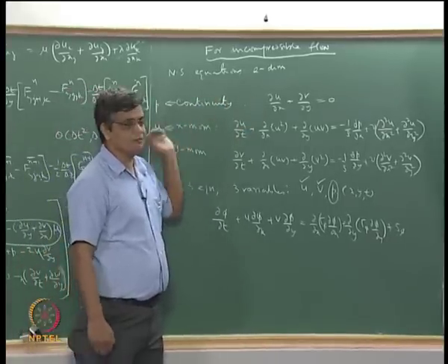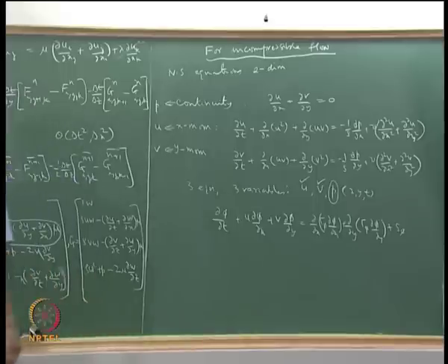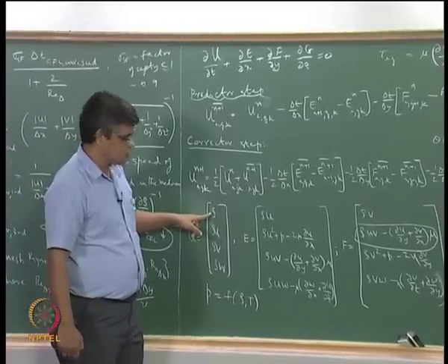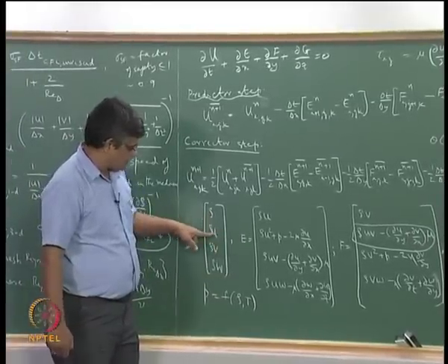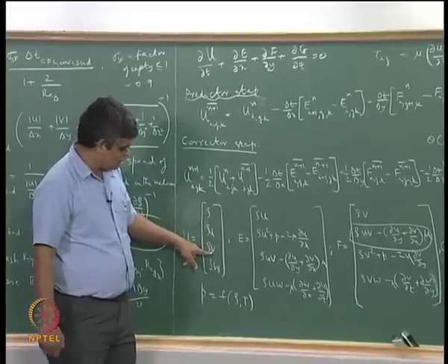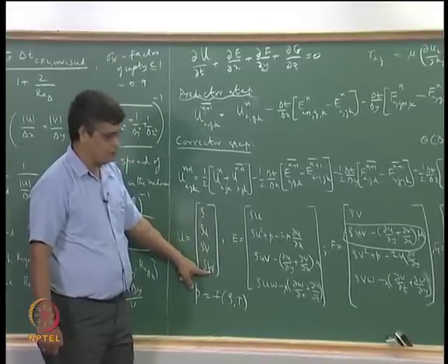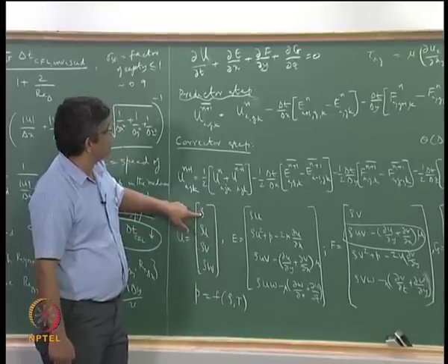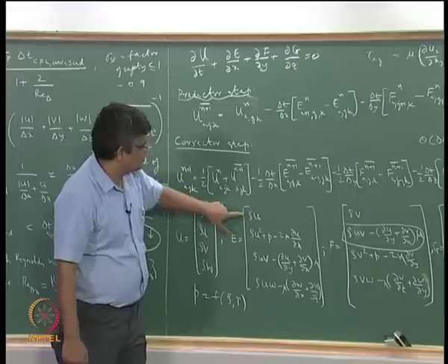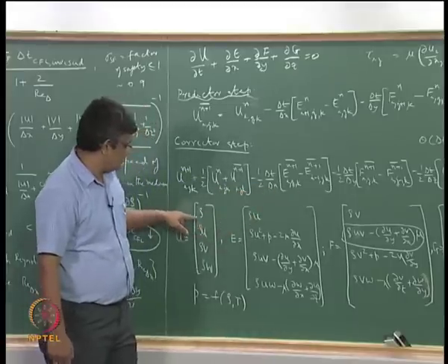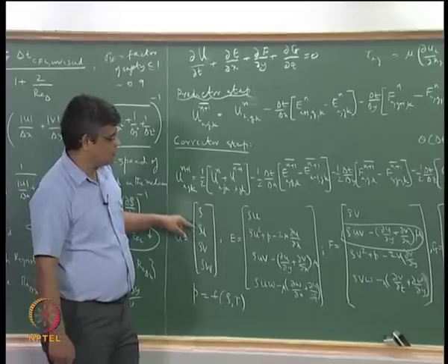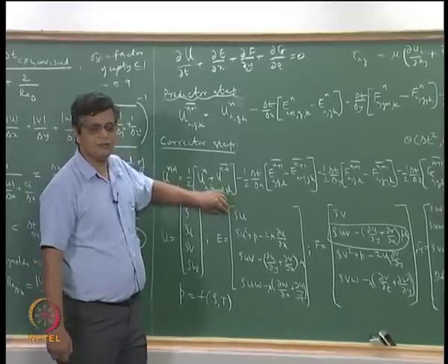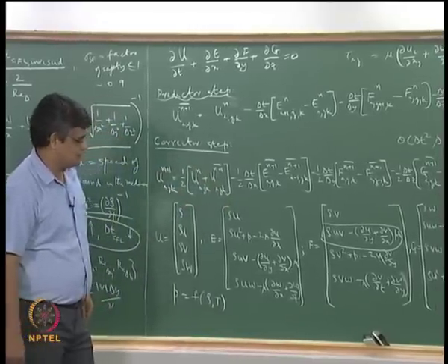We do not have the problem in compressible flow, because in compressible flow we are not solving directly for pressure. We are solving the continuity equation for rho, and the x momentum equation for u, the y momentum equation for v and the z momentum equation for w. So we are making use of the natural equations here, and rho appears in the continuity equation because you have d rho by dt plus all those things. So the continuity equation, which is used to evaluate the 4th variable, rho, has the corresponding variable appearing as the main term.